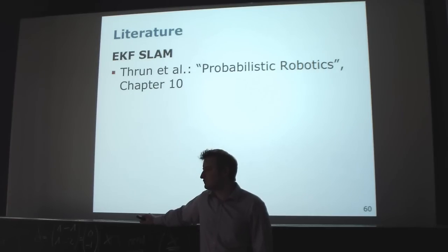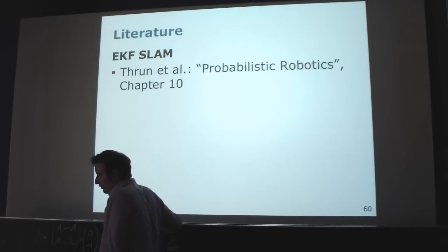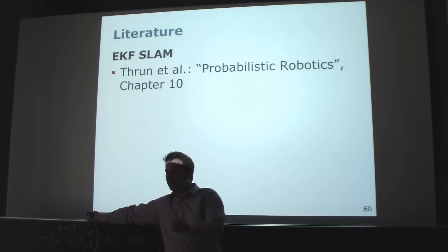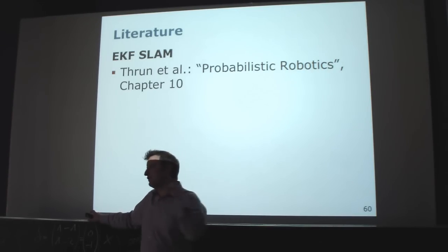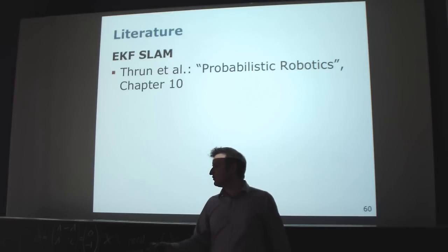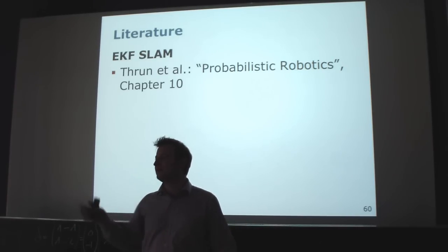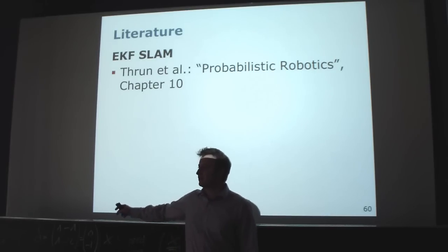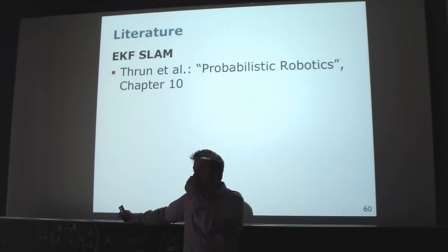But that one that goes from here to Patterson, that was a SLAM? Yes, it was a two-layered approach. On the one hand, you can joystick the robot at some point to build a map, and then you can actually navigate in the map you built once. There is also the possibility of extending the map. If you know parts of the map, you can do some kind of exploration actions. But it may be that this exploration action fails, and you have to go back and try an alternative path. So we had some heuristics in there, but some background knowledge was required. Or actually a map built by steering the robot once and then revisiting that map, localizing in that map, and navigating in order to do the navigation task. But at the first point in time, at least in the system as we presented it here at Freiburg, it had a map that it previously recorded.